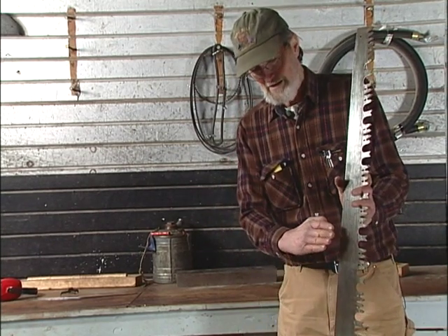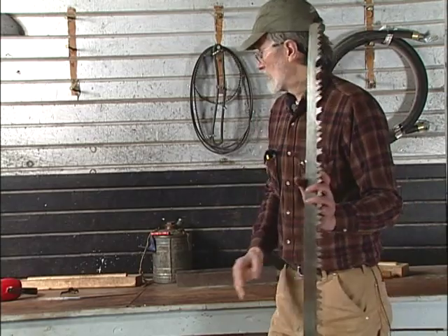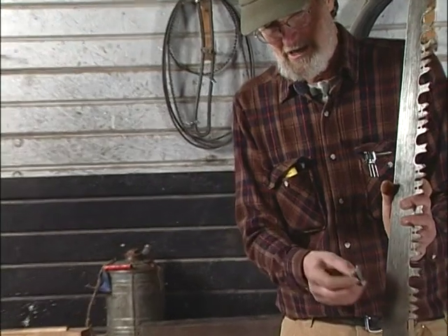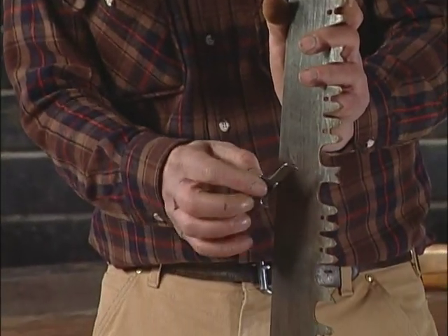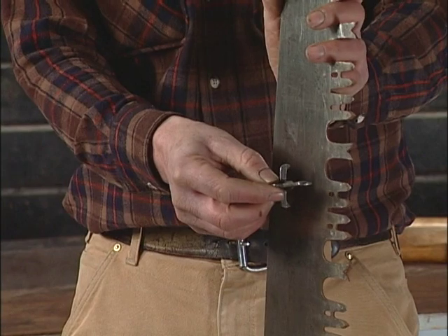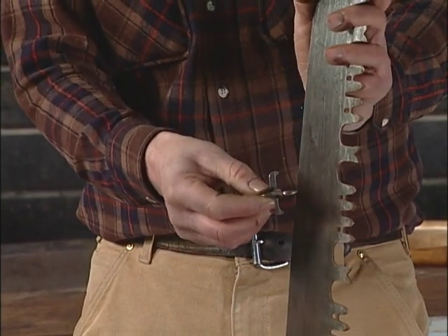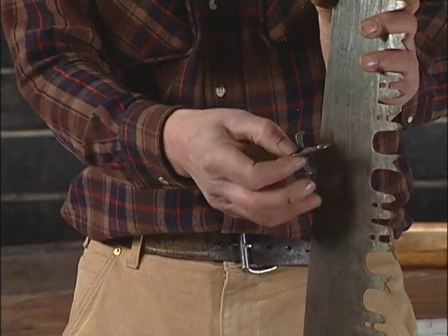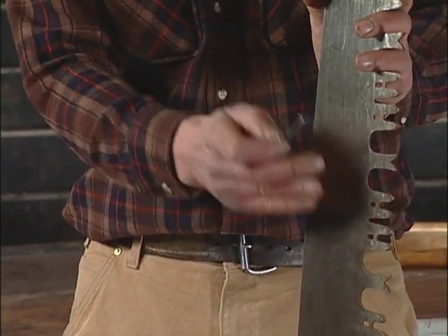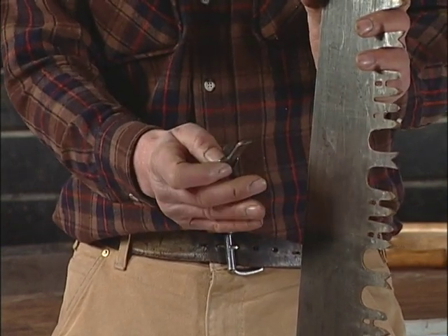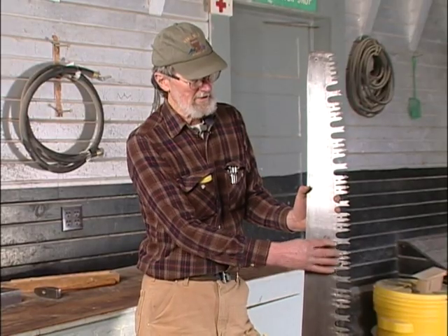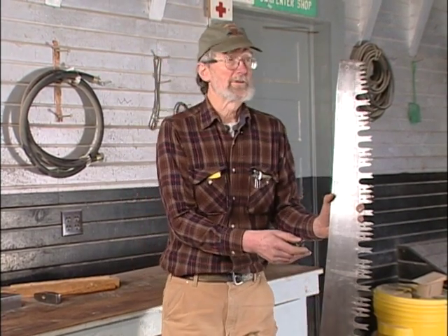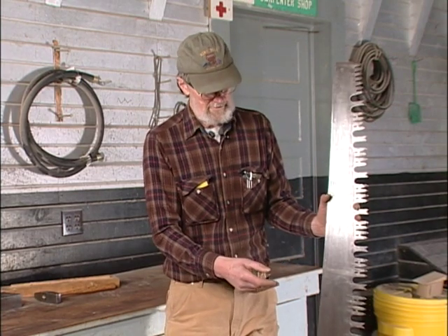if your saw has a little bit of a kink in it and you put your spider on there for checking the set, the spider will measure differently if there's a kink in it or not. And the result of that will be, if you set your saw to the adjustment of the spider, that your set for each individual tooth will be different, which is important to avoid. You want the teeth of the saw, your cutter teeth, to all have the same set. So those are the primary reasons that you want to make sure that your saw is straight.